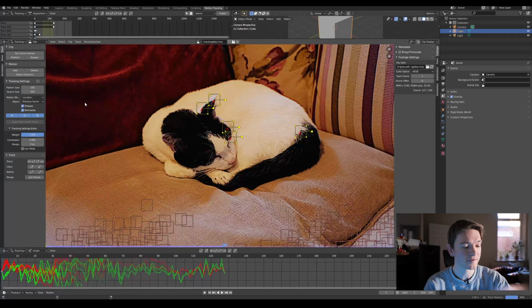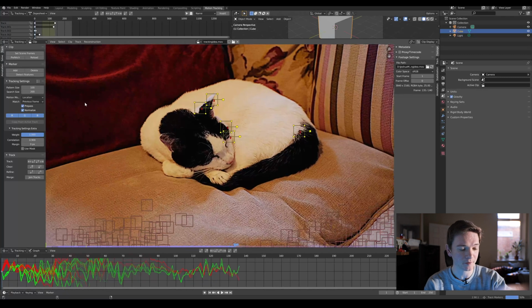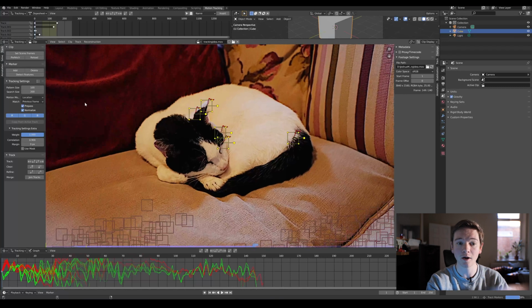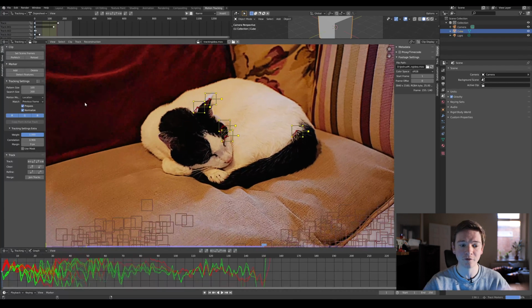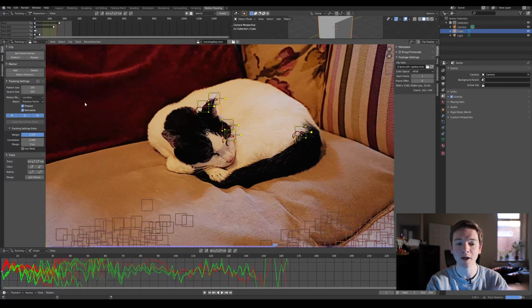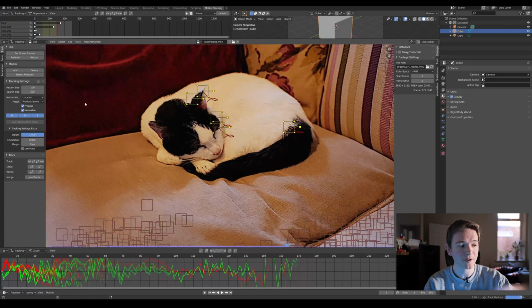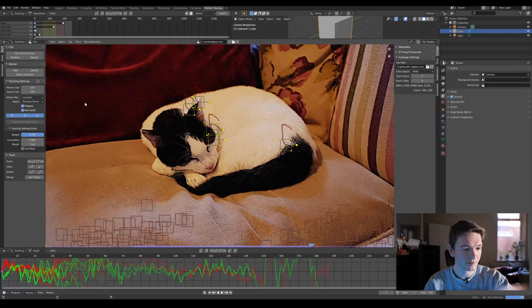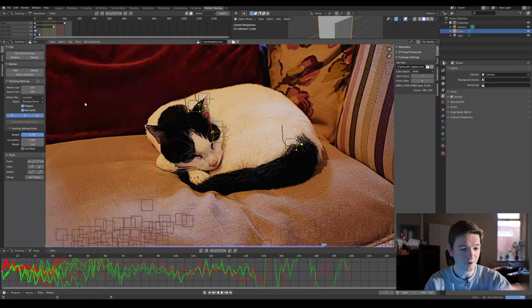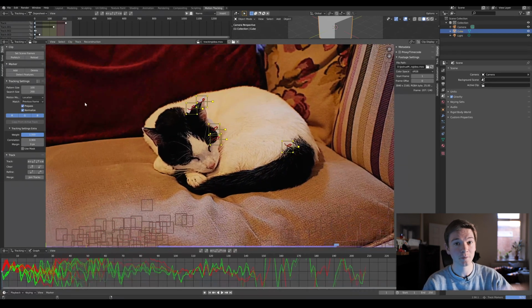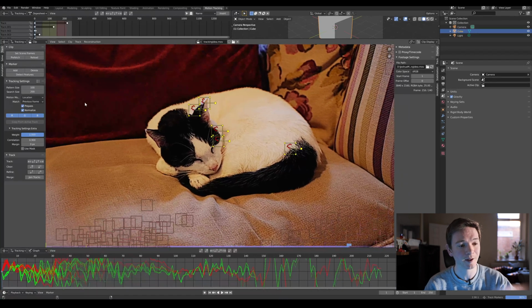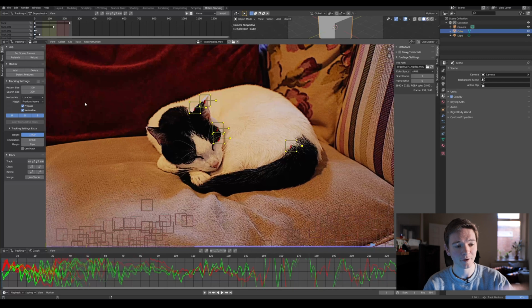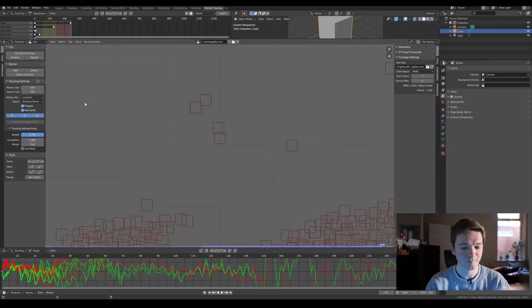As you can see, the graph starts off quite thick and then starts to peter out as it goes forwards. That's because some of the tracking markers are gone from the footage, they've moved out of frame, or have not held in relation to the correlation we set of 0.9. So we are actually currently left with 5 tracking points in this first track, which isn't enough because Blender needs 8 solid tracks for it to be able to solve this camera motion.